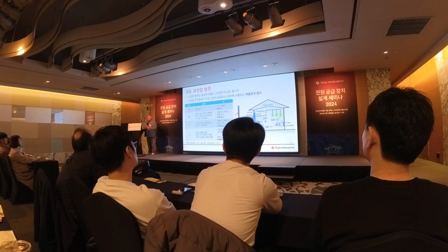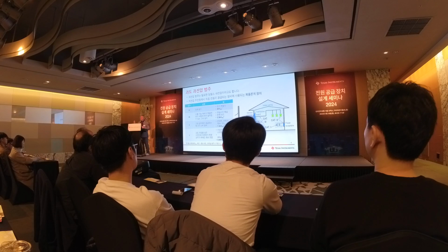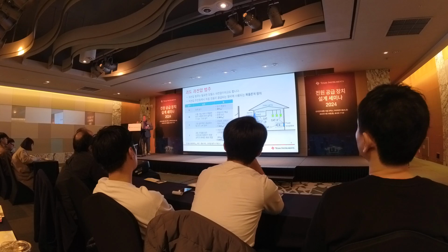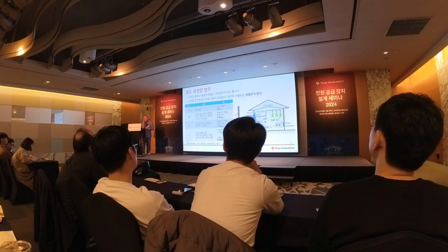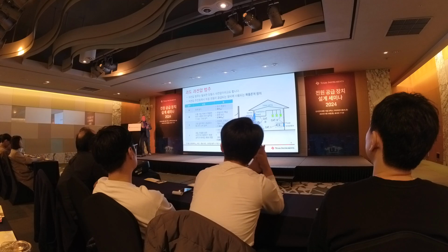Okay, let's talk about the transient overvoltage category. So the overvoltage category, also referred to as the required impulse withstand voltage. So there are 4 categories for the higher overvoltage level. And it has to do with how close you are to the energizing source.